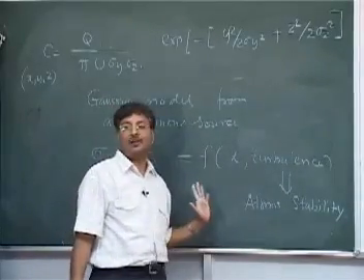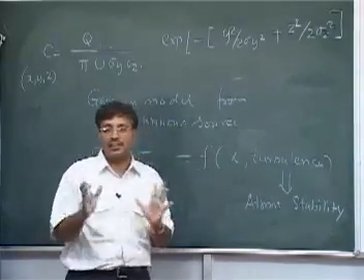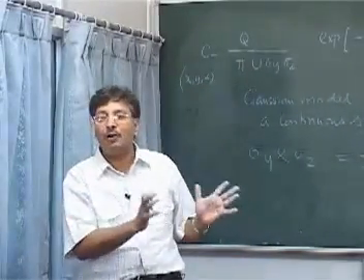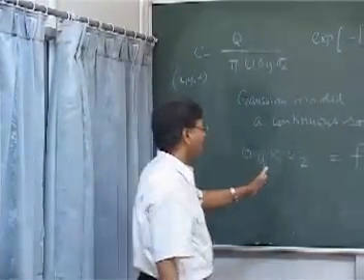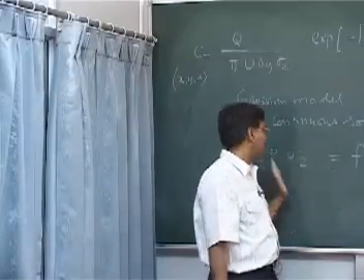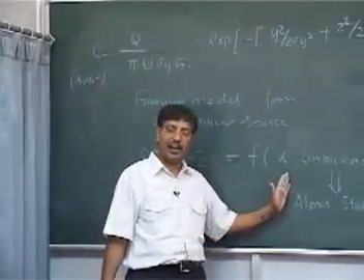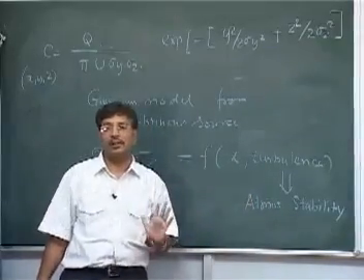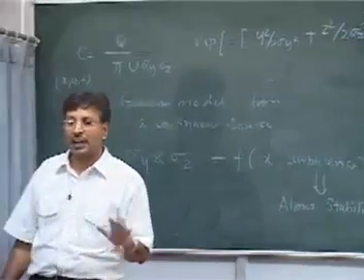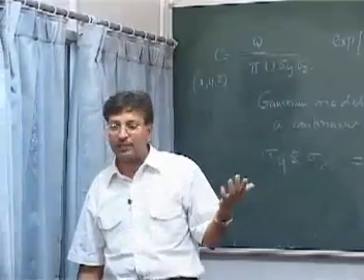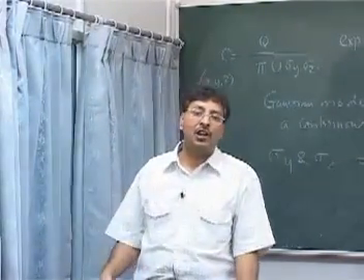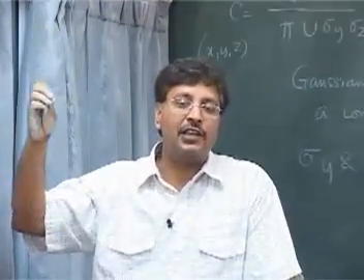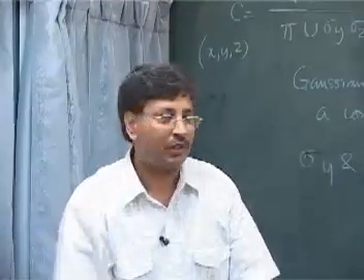How it is governed, we'll see later, but as I say always in the class, we have the qualitative and quantitative. At least in the qualitative sense, what function it is we don't know, but you will agree with me sigma y and sigma z are a function of x and turbulence. And turbulence we have defined as the stability so far in the class. And stability we can find out through many ways. One of the ways was the Turner method, to get the data from the airport and find out the stability from any place in the world. We'll stop there. Thank you very much.